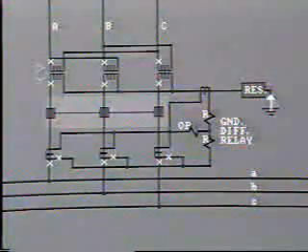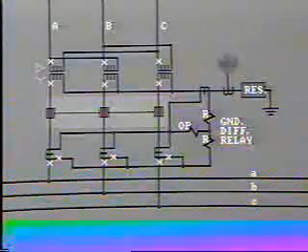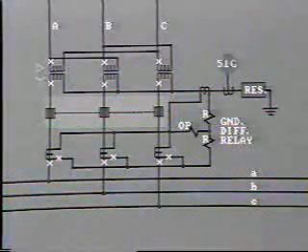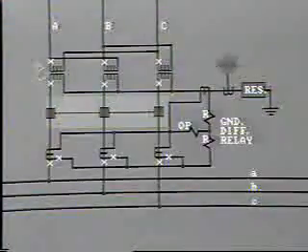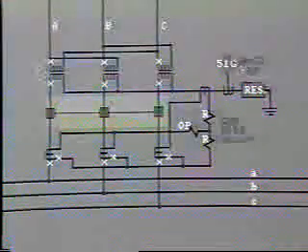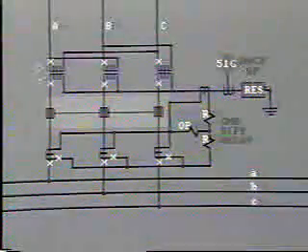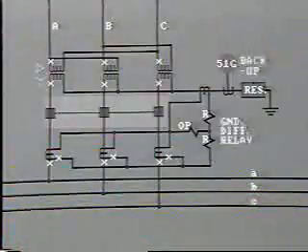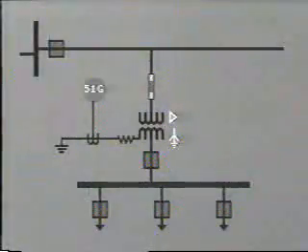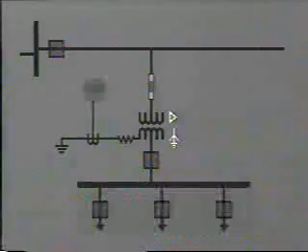Quite often with this arrangement, an additional time overcurrent ground relay, 51G, is installed in the neutral. This acts as backup for the transformer ground differential and also as backup for ground faults out on the feeders. It must be correctly coordinated with protection on the feeders.